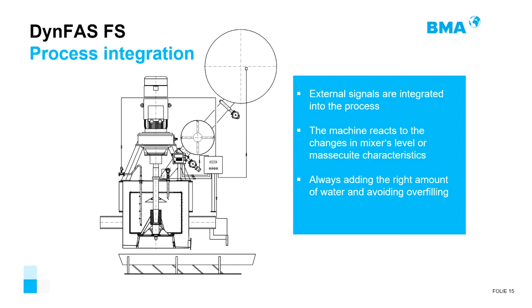because with this information and a little bit of software capabilities, we are modifying the time and the grade of the feeding valve and measuring automatically the layer thickness so that we can go for each cycle, for each batch, to 95% of the basket capability.